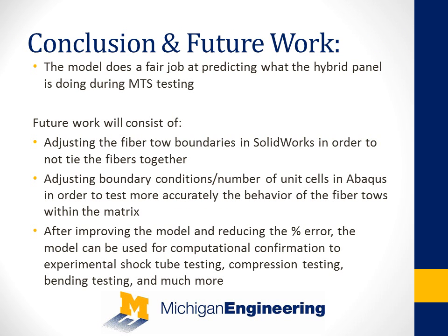So what's next in this test? Well, the model we have does a fair job at predicting what the hybrid panel is doing during the MTS testing. The next step would be to see if we can refine the model in order to decrease the percent errors that we're getting, especially in the strains and the Poisson's ratios.